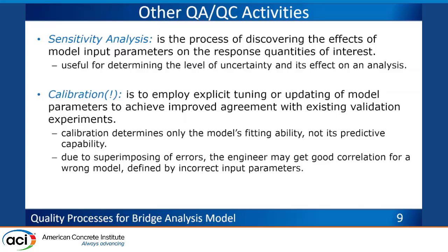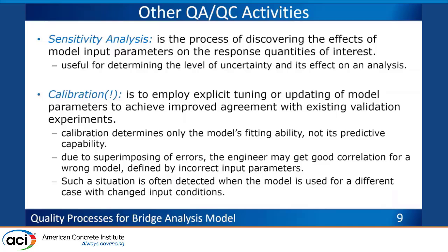You see that, yes, you are getting a very good result. You calibrated to a specific type of model, but if you model something similar, the same category but a different system, you realize it's completely off, because you superimposed errors to get good results in one application, but really bad results in other applications. So calibration should be used with a lot of caution.